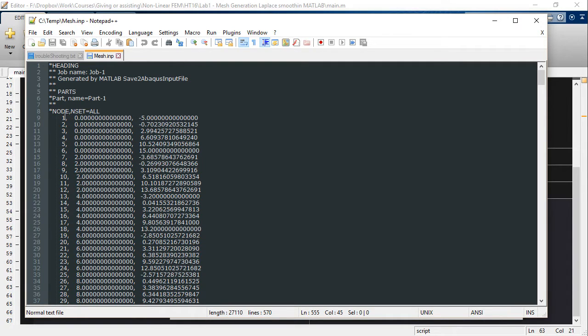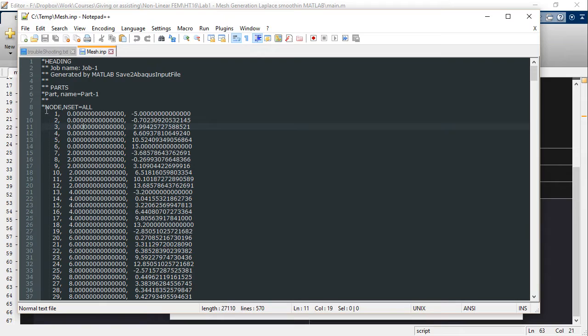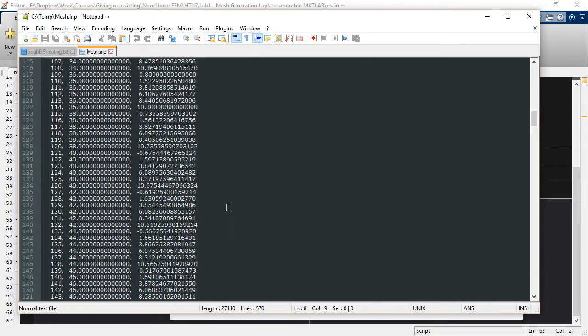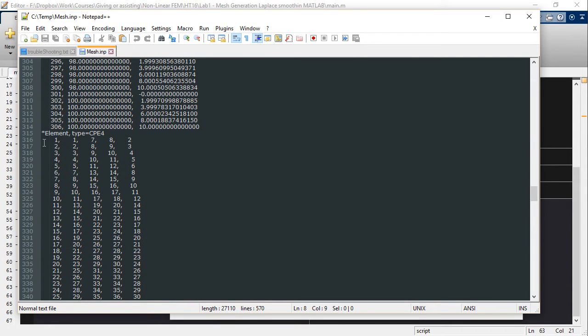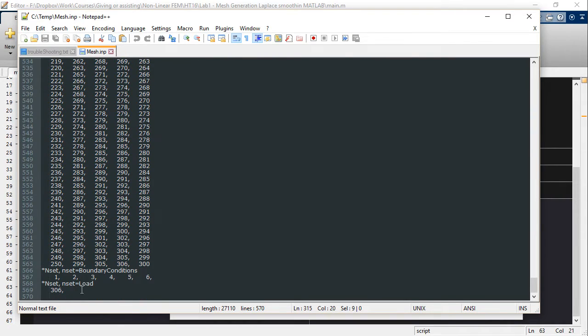We will get basically whatever we want, but now the functionality is that we will get the basic mesh, and that's basically just the node connections, all of the coordinates, the points, the nodes. This is what we have here, the node, and the element connectivity, which is further down here. So we have the element here, we have a certain type of element, and every row is one element. And then optionally we have two sets here, two node sets named boundary conditions and loads.